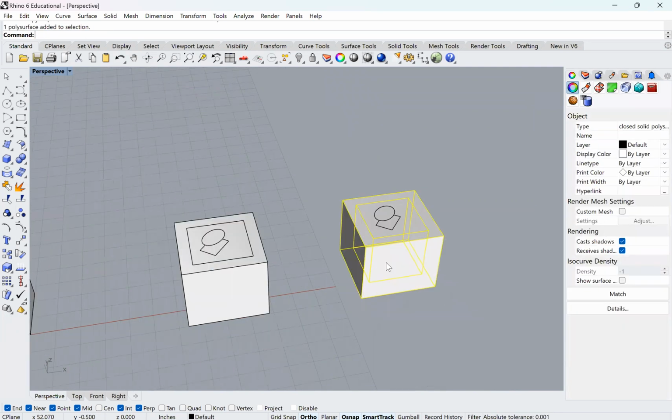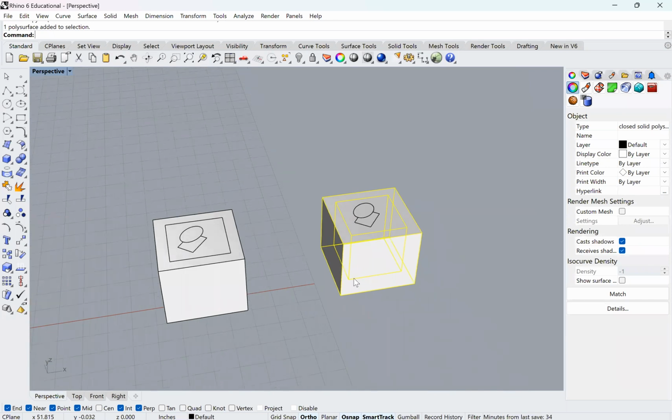How do we take it out? Yeah, exactly. So the box that we make, we'll do that next week when we're in the shop. But the way to build this box is you build it out of pieces of MDF. But we can't glue the box together. We have to screw it together. And that way, once the cast is ready, we unscrew it and we can take the box apart, like all the exterior of the box.